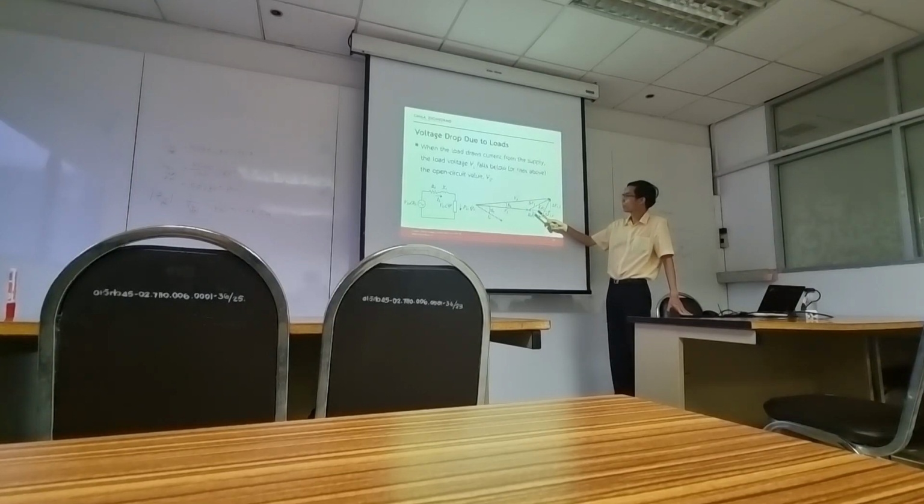You can calculate the voltage drop, represented by delta VL. Delta VL is just RSIL plus jXSIL. You can separate it into the real part, delta VLR, and the imaginary part, delta VLX, something like this.